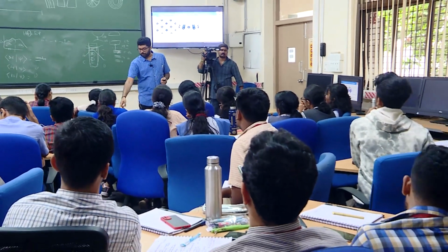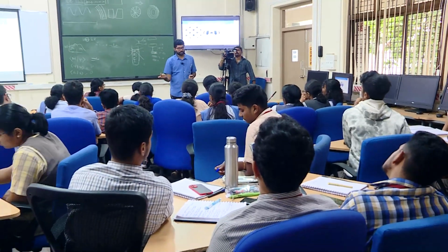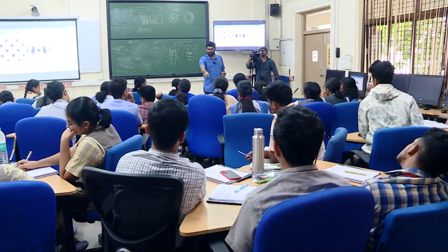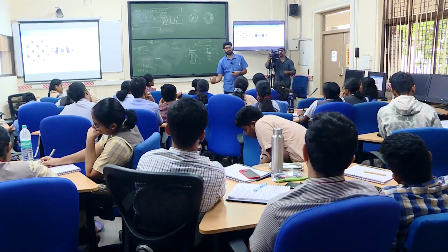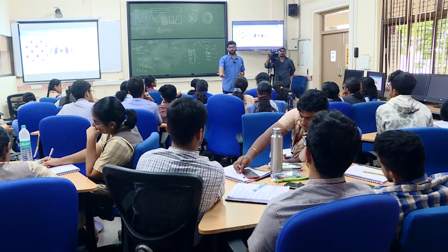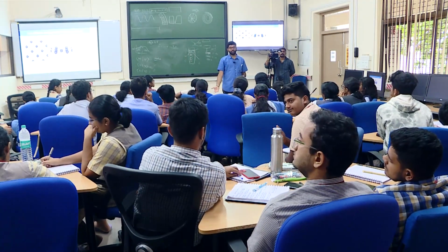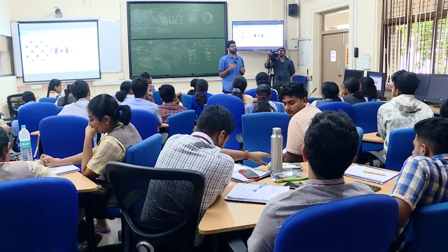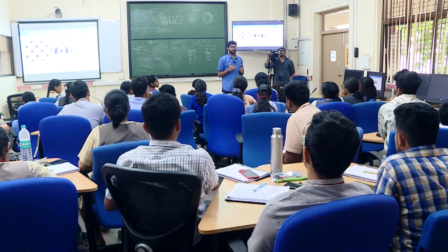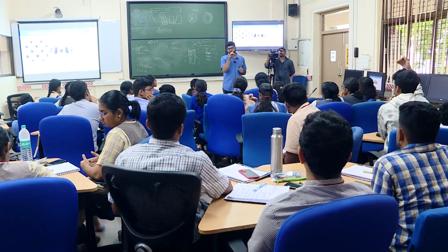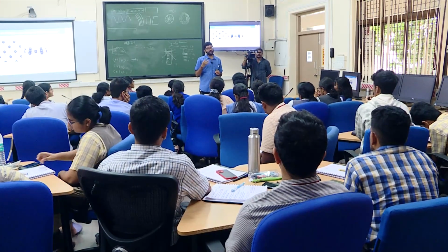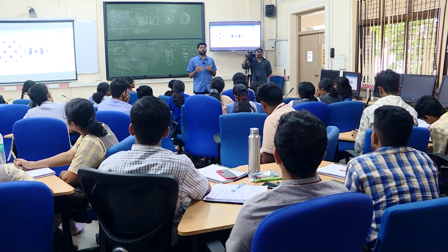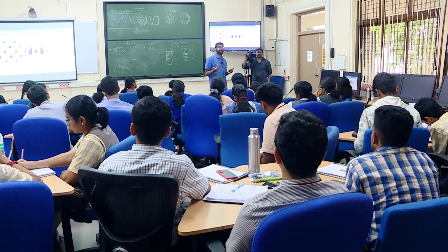Again, if this person has to get up from this site and go to the next site, and the difference between the sites is very less, then it is easy for the person to move from this place to the other place. It's not about how comfortable it is. How easy to move is the question we are asking. So it's about the difference in energies between S3, S1 and S2. If they are low, the migration energy barrier will be low.